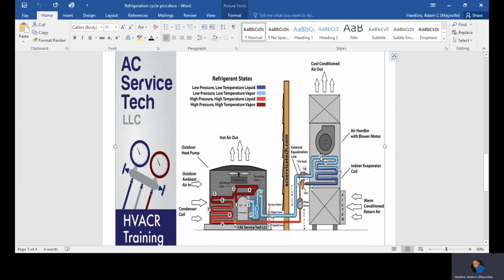That basic air conditioning split system is going to have an outdoor unit and an indoor unit. It's also going to have some sort of blower that moves air across an evaporator. So that evaporator is where your heat is going to be captured. And then your outdoor unit has a coil around it, or in this case, it's kind of over here on the side just to show you. That coil is your condenser coil, and that's where the heat's going to be rejected.